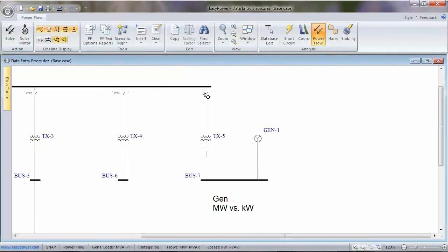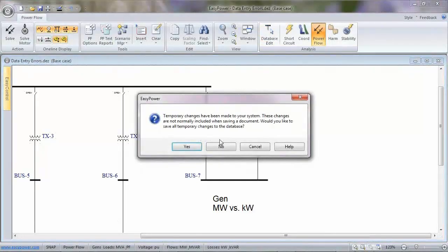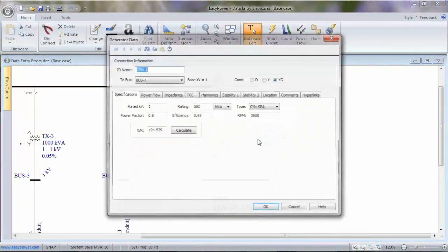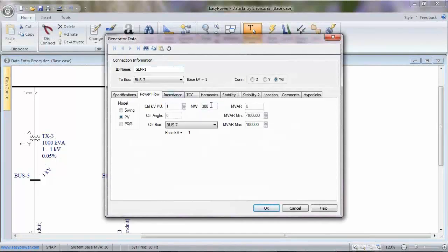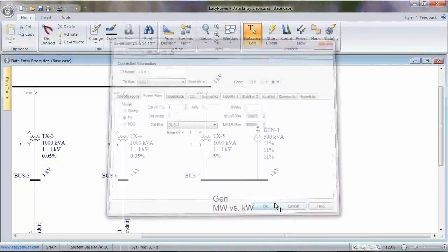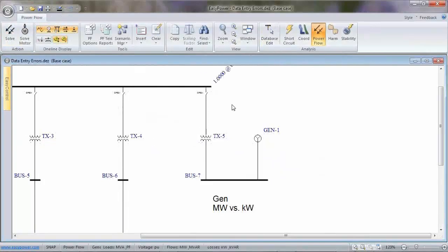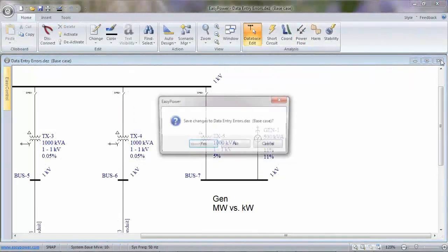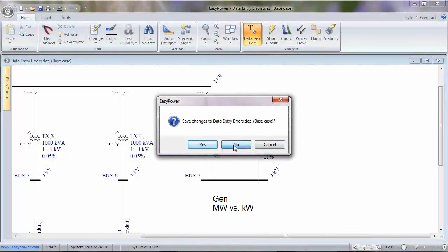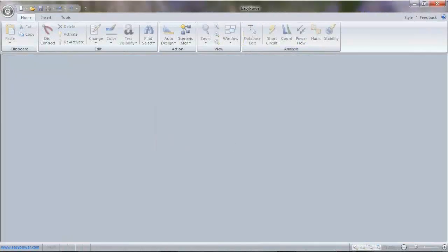Okay. Again, all we would have had to do is change that back to kVA, and it would work, right? Put this kVA, and then change our power flow to 0.3. And yes, we get a solution. Okay. Now let's look at a couple more things.